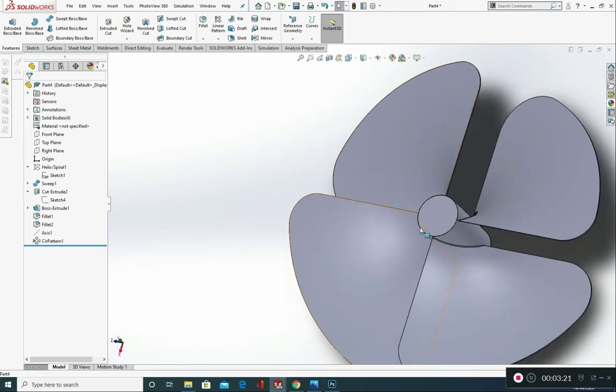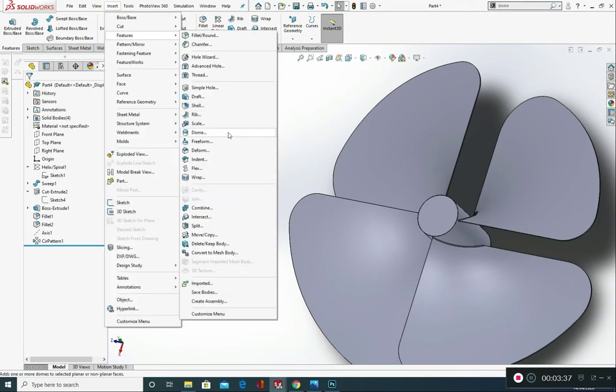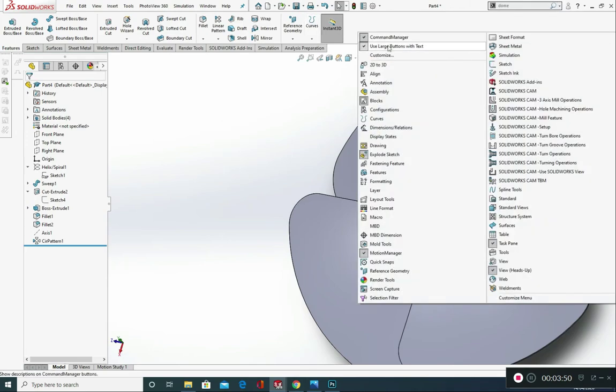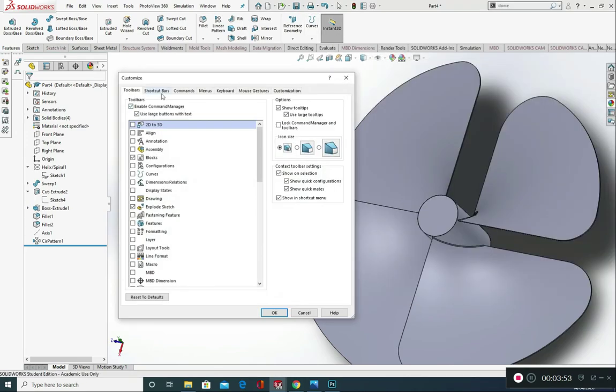And then let's create a little dome feature on the top of this. So one way of doing that would be type in here dome, okay, and select it. Another way is to find out where it is. You could go dome, search, click on the eye, and it'll tell you it's in Insert, Features, and Dome. Okay, and then you could go ahead and grab that.